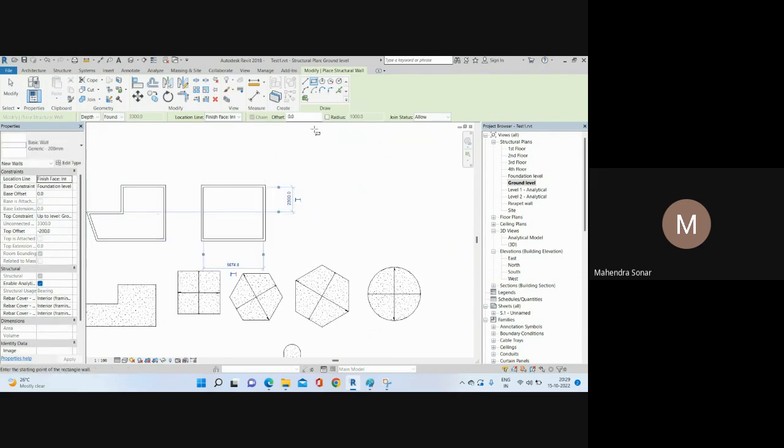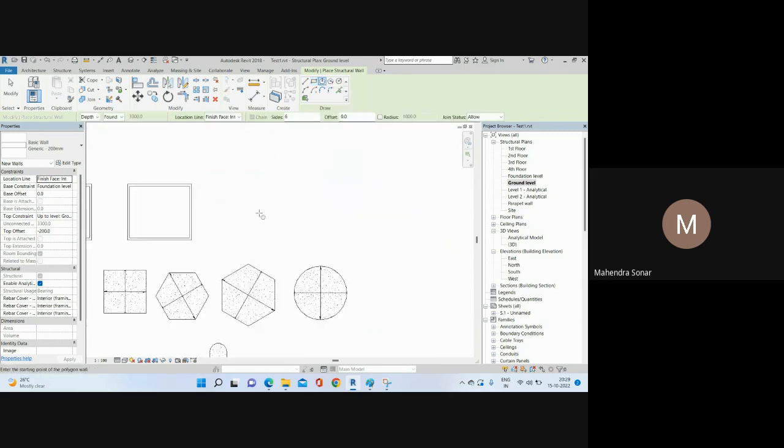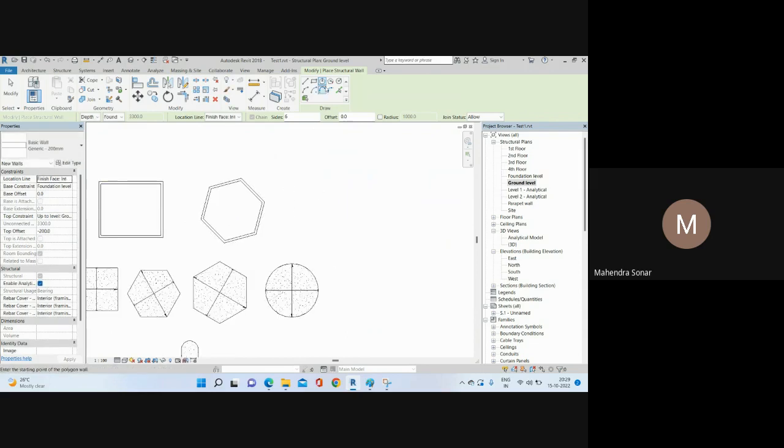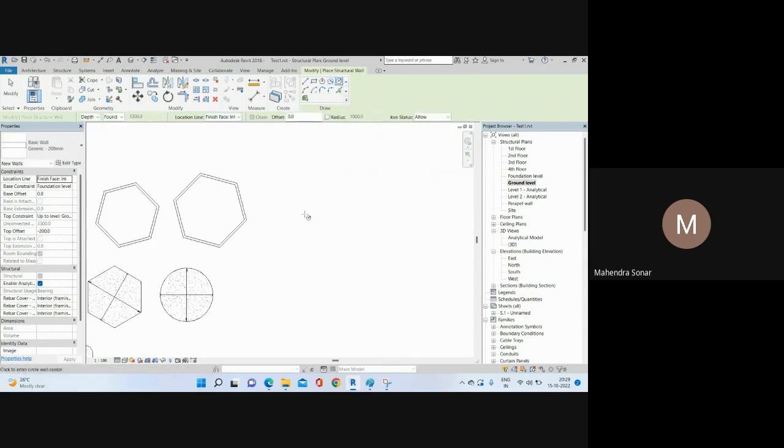Okay, then after that, if you want to add your walls with this polygon option, select, give the radius like that. Then different also, give select center of polygon, give the radius. Then if you want to add circular, suppose if you design some circular tank, so you can add the circular wall. And these are the different curve walls.